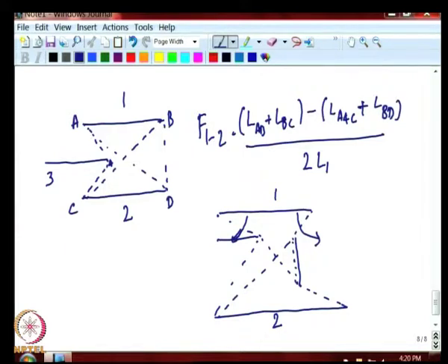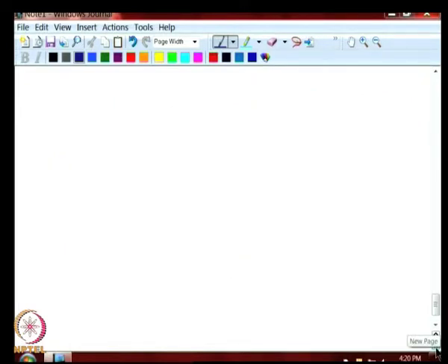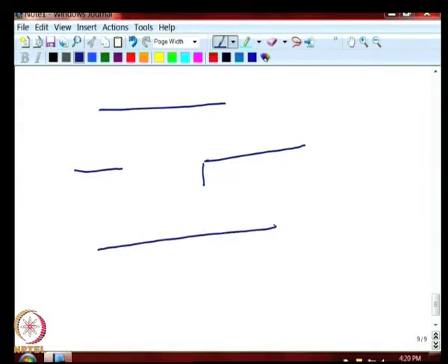Now, let me just take one more example to complete our discussion, so that there is sufficient. So, there are 2 obstructions here, one here and one here like this, and one here like this. So, you can see correctly this should be one parallel string, that is very obvious. The second parallel string has to keep out this obstruction. So, you draw it like that, draw over this and then over this. So, that is very easy. In this case, crossing is very easy, this one and this one.